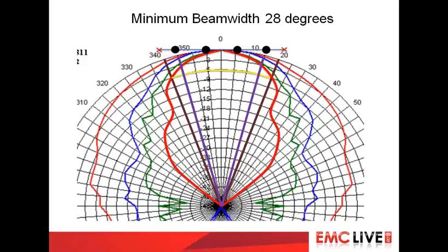So now, we've actually gained quite a lot of information here. We've got a large don't care area. If it falls outside this slice of cake defined by the two brown lines, we really don't care. And we've defined a keep out area, where no matter how hard we try, if there's more than 6 dB difference between what's at the bore side there and what would turn up at those two red crosses, we've lost already. There's no way we can fall within the limits defined by the standard. And this is quite useful information when you're designing, because people are quick to blame things on room effects and so forth, and you are in fact allowed by the standard to drop 4 of those calibration points. But where I'm going here is, if in basic theory it cannot be achieved, when you put it in that chamber, it can only be worse. It cannot get better. You're on a hiding to nothing. You can't win.